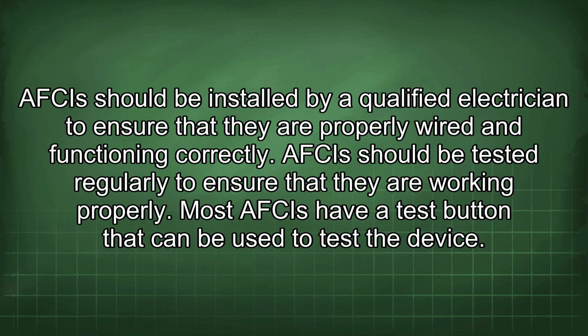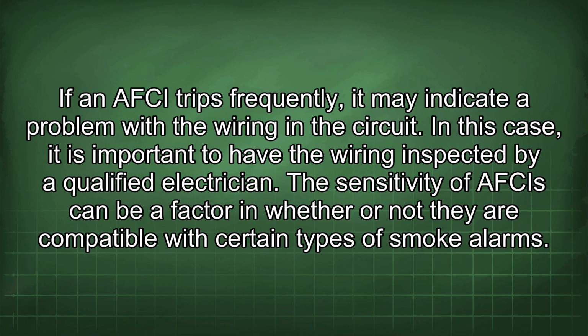AFCIs should be installed by a qualified electrician to ensure that they are properly wired and functioning correctly. AFCIs should be tested regularly to ensure that they are working properly. Most AFCIs have a test button that can be used to test the device. If an AFCI trips frequently, it may indicate a problem with the wiring in the circuit. In this case, it is important to have the wiring inspected by a qualified electrician.